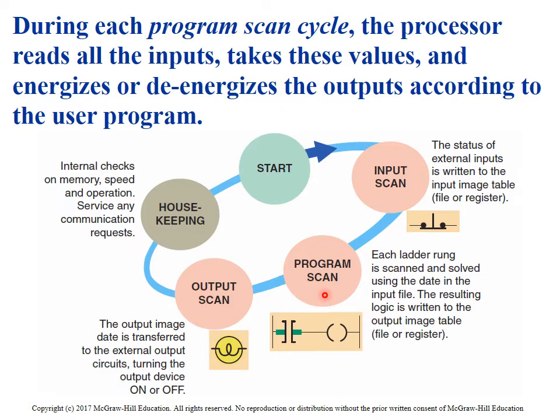Also, I need you to be aware that in the latest 5000 version of the PLC, they do what they call an asynchronous scan, which means they do all this at the same time. They're not going through the process of scanning an input, then updating the program, then updating the outputs. It's constantly reading the inputs, constantly running the program, and constantly updating the outputs, all at the same time. That improves the process itself.